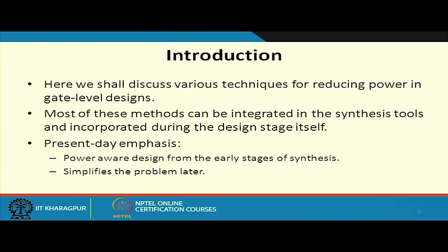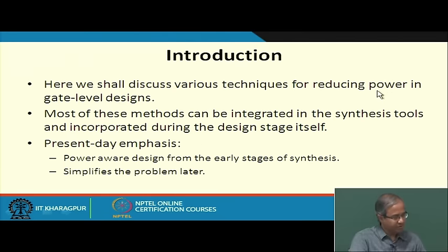Now, the advantage of these gate level design techniques for reducing power is that these methods can be quite easily integrated as part of the synthesis tools, like the CAD tools. And of course, one very important design principle that is being followed is that you try to incorporate a power aware design philosophy from the very beginning.